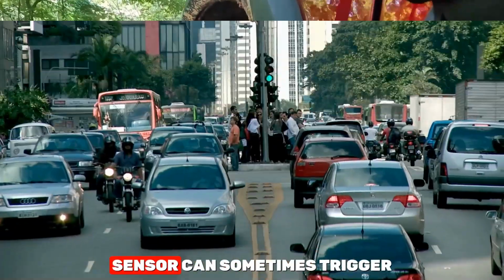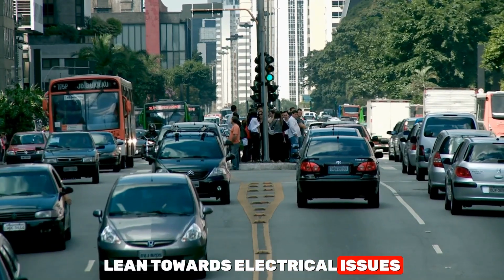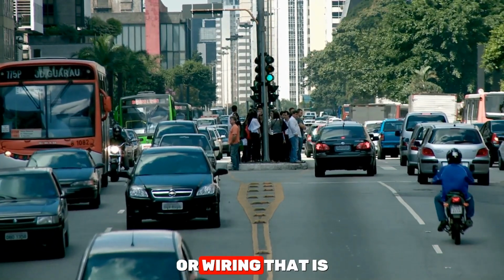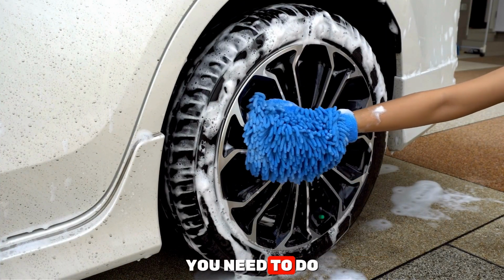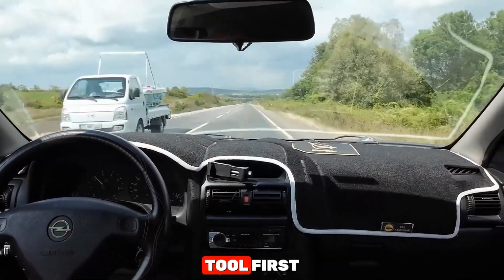While a bad oxygen sensor can sometimes trigger this, the causes often lean towards electrical issues like a defective controller, a programming error, or wiring that is burnt or chafed. Before you go replacing the computer, which requires expensive reprogramming, you need to do some troubleshooting. You will need a digital volt ohmmeter and a scan tool.